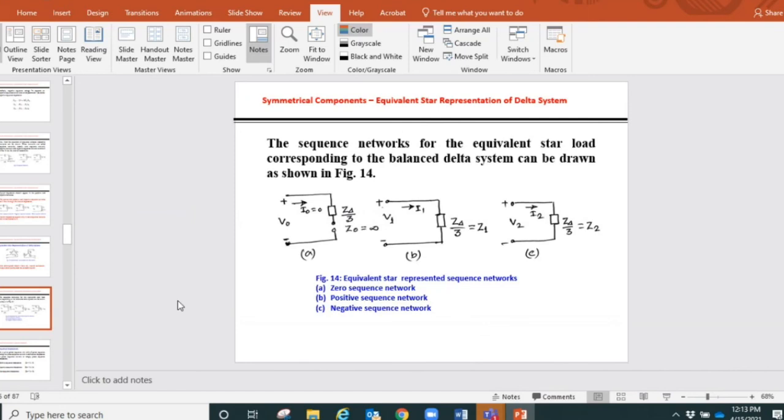Looking at light bulbs, which are incandescent or arc lamps, they will flicker. If we look at the impedance, it will increase if we increase the frequency. Also, I'm sure when you run a motor or a transformer, you hear a buzzing sound. It is from magnetostriction that happens in the core winding. They will start buzzing, the humming sound that we hear when you go to a substation or nearby a transformer and put our ear there. That noise comes from the frequency. Then we come to the generator, at which speed we can run them. For some generators, it's challenging to run them at low speed. For some generators, it's challenging to run them at higher speed.